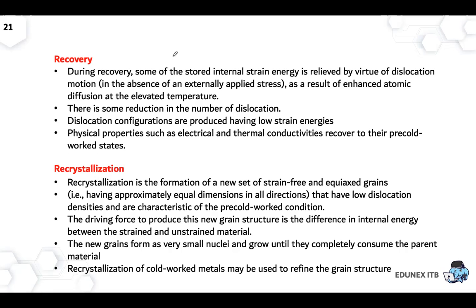Then during the recovery, there will be some reduction in the number of dislocations, and dislocation configurations will be produced with low strain energy. The physical properties such as electrical and thermal conductivity will recover to their pre-cold-work states. After the recovery, the next step is recrystallization.